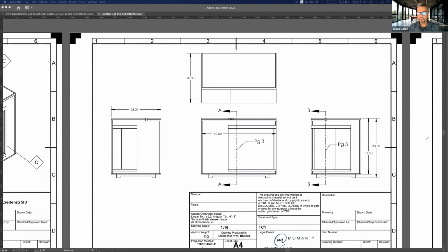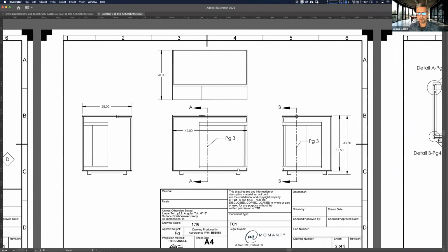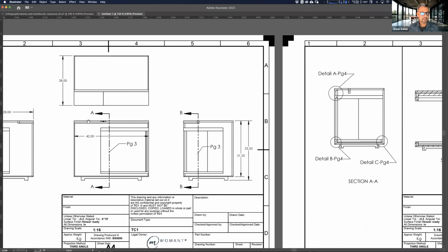Okay. The largest dimension is usually on the outside. So you see the larger dimension on the outside. Anything smaller than that should be on the inside of that. This is showing the cabinet without the feet, that dimension, and then with the feet, that's the entire height down here. So that's one of those things you should definitely take note of, exactly how those dimensions are arranged. The other thing is the sections.